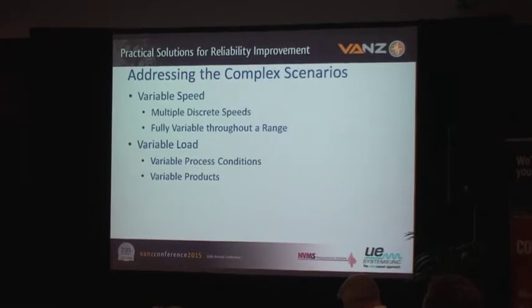So what does that mean? We owe it to ourselves to record a few other parameters in addition to the vibration data. I need to record the speed. I need to record the load. I may need to record several other parameters in order to assure myself that I'm putting myself in a position to compare data from consistent operating states from one time to the next. And if I took data today, it might be at one speed load condition. I take data tomorrow, it might be at a different speed load condition, et cetera, et cetera.